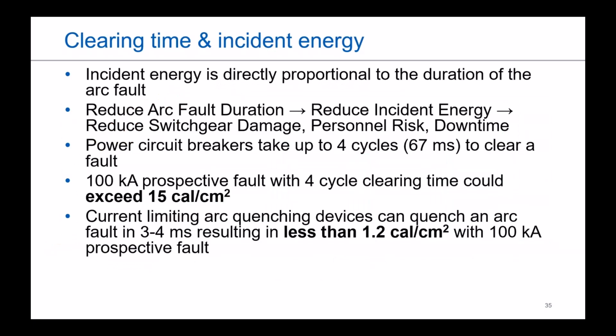Just to circle back and reiterate, talking about clearing time and incident energy specifically, incident energy is going to be directly proportional to how long your arc fault is allowed to run wild and rampant within the gear. And obviously, if you can reduce the amount of time the arc fault lasts, it gives you lower incident energy, which means you're going to see less damage, there's less risk to your personnel, and ultimately it should mean lower downtime after an event.